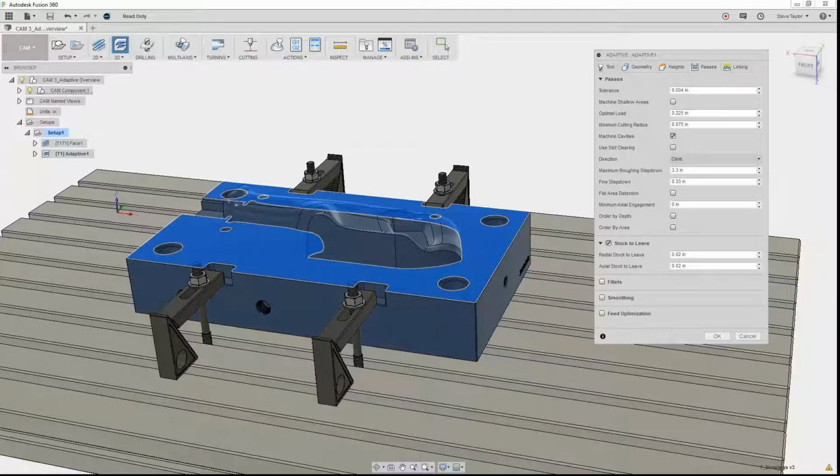This will also ensure that we are not just using the first quarter inch of the flute. When you're machining, if you're not careful, you might have a tool that's got a long flute length. If you're only cutting all the time on the very bottom of that flute length, then that's where it's going to wear, and you're going to get uneven wear. So if you then come to machine something later on down the line using that same tool and it's got uneven wear, you're not going to get the same accuracy or the same model that you want.